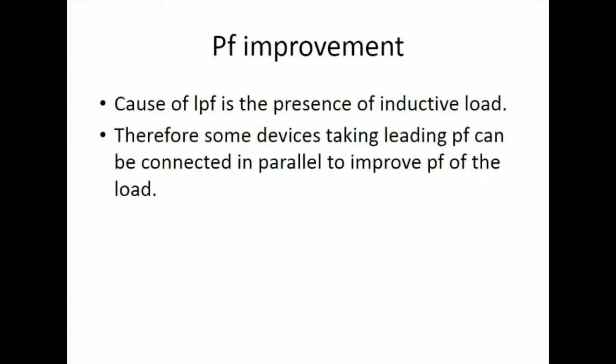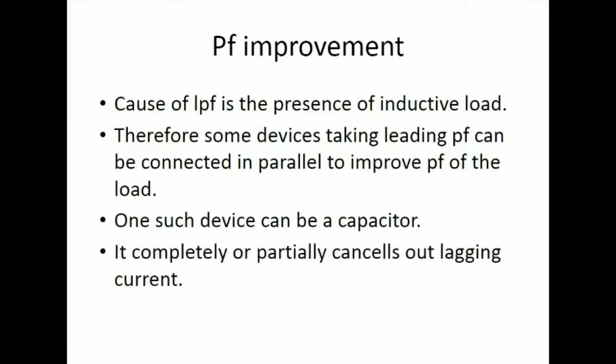So, inductive loads produce lagging power factor, and if we have some equipment having leading power factor in the same system, these two will get cancelled. The lagging effect will be compensated by the leading effect and power factor can be improved. One such device can be a capacitor that produces power factor improvement. It can completely or partially eliminate the lagging effect.